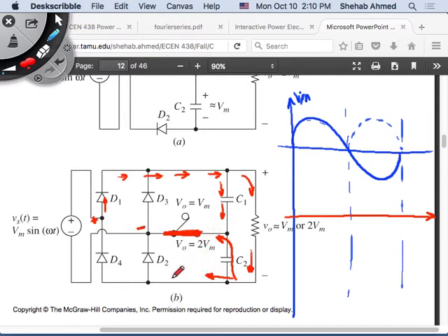It cannot go back through diode D4, because this is the most positive potential, so D4 is off for sure. But initially it can go back through D2. It's an easier route if the capacitor is discharged, right? If the capacitor is discharged, capacitor is an impedance.